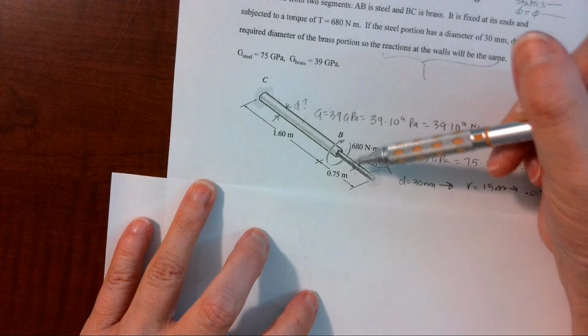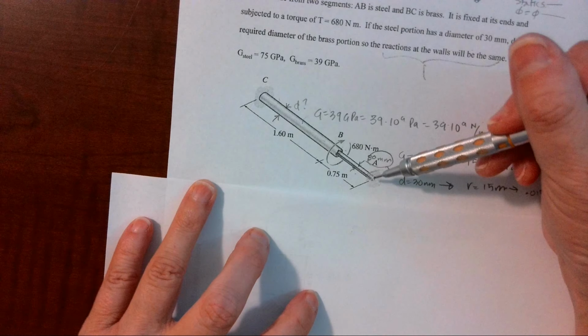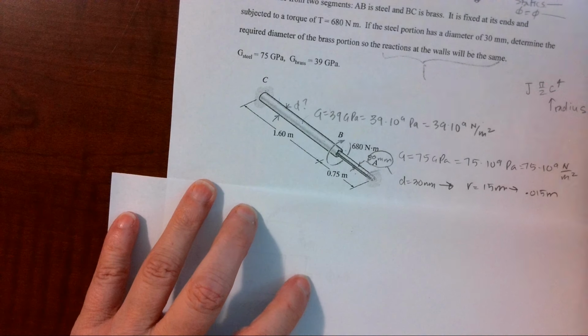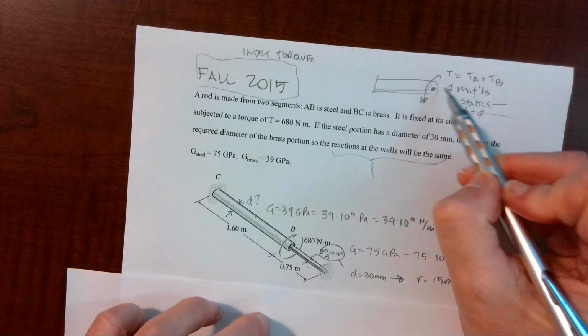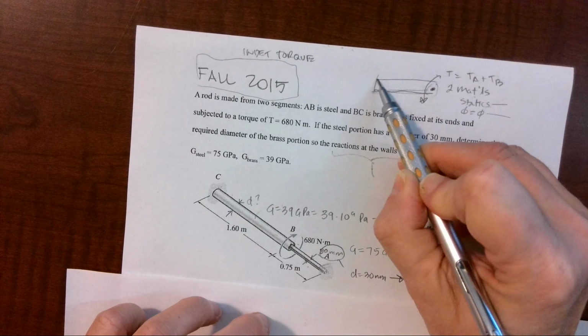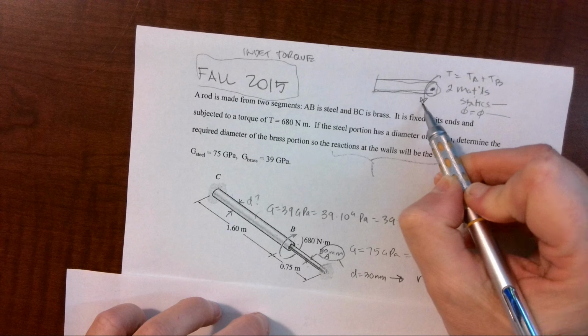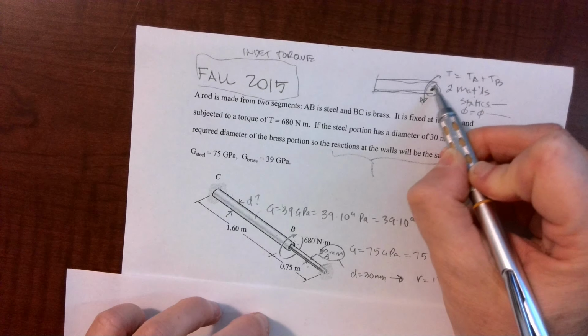have different lengths, different materials, different radius. So I don't know necessarily what my torque at A and my torque at C, I don't know how that's going to be distributed. This is a lot like the practice one you guys had yesterday, where I had a core and then I had an outer sleeve. And I know that the applied torque was some amount, and I needed to know how much torque material A and material B carried.